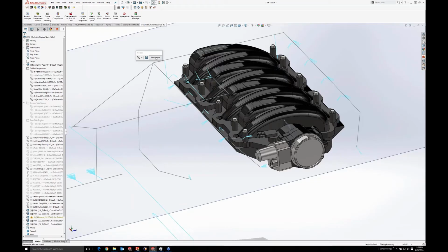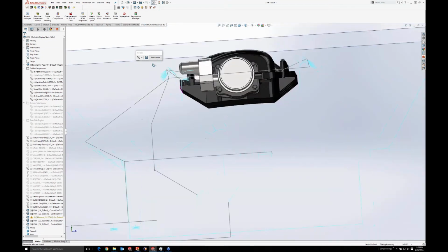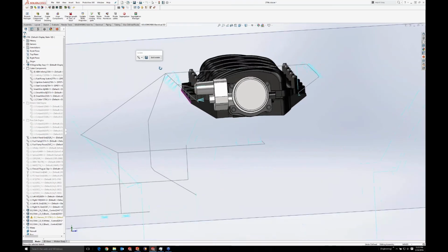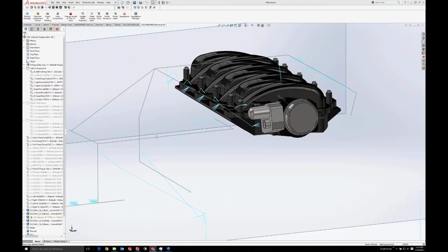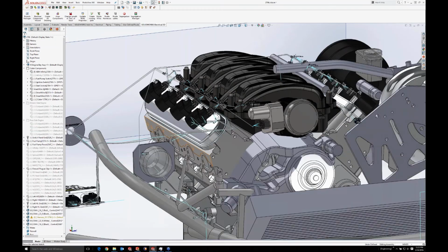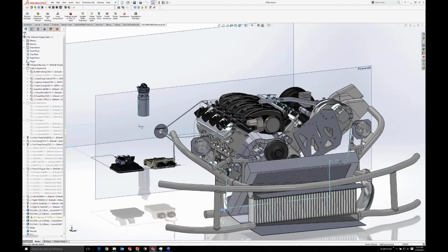That way, I don't have to manually tell SOLIDWORKS each time I'd like to use that Panduit where I'd like to route. So with my intake manifold, I said, well, hey, I usually have some injectors coming out of these holes here. I have some coil packs over here on the side. So give me a route path, I don't know what I did, 3 inches out from the corners there. I'll show you in a second. It actually used that and did a pretty good job.